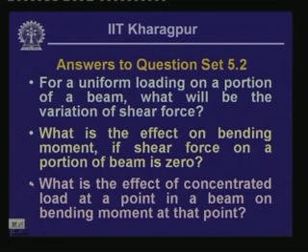Now, the last question was, what is the effect of a concentrated load at a point in a beam on the bending moment at that point. If you remember, in the last lesson we discussed the effects of different kinds of loads on the shear force and bending moment at a particular section: the uniformly distributed load, the concentrated load, or the concentrated moment. Where we had the concentrated load in a particular segment, we evaluated the shear force and bending moment on the left of the load, and on the right of the concentrated load.